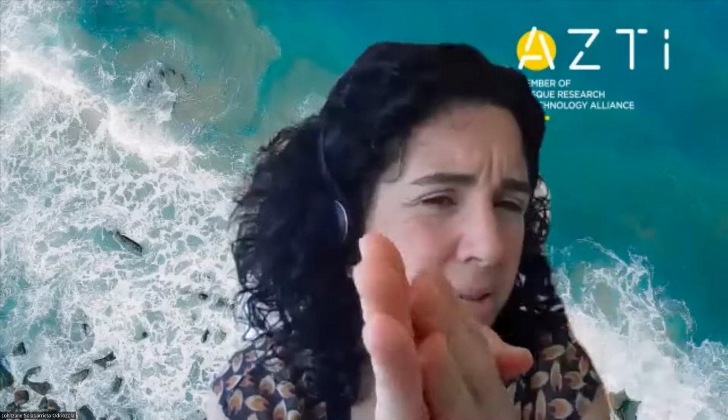Yeah. So thank you for the question. Thank you, because this was part of my PhD thesis, and it took a really long time. So we compared not only, this was just an example of the validation, you can see that this was a single point here. I showed you the Matxitxako buoy. We did the same with the Donostia buoy. We measured not only on the surface, but also in deeper layers. We saw that during the stratification periods, we could see differences between the surface and the deeper layers, but during the mixing periods, we could observe the intensification of the deeper currents also at the surface, and it was also shown in the radar.